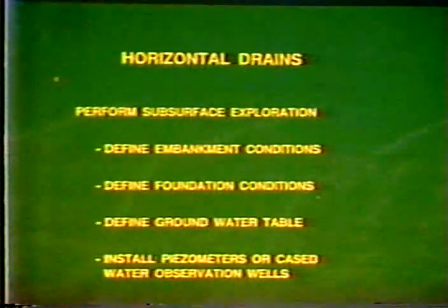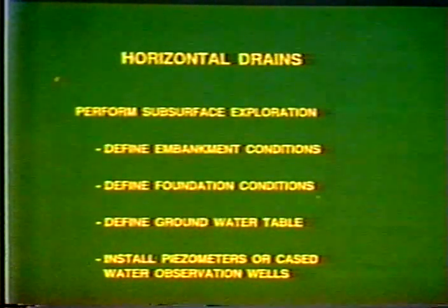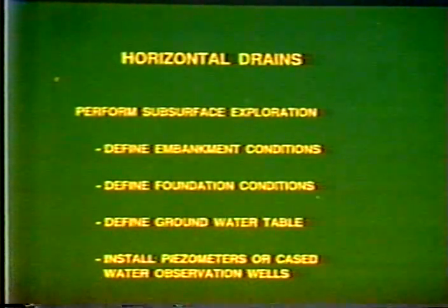Another thing, when you install horizontal drains, you always need to do some footwork. You need to define the embankment conditions, the foundation conditions, and the groundwater table. These things are essential. And it's always good to install, as Dave talked about, piezometers or water observation wells.